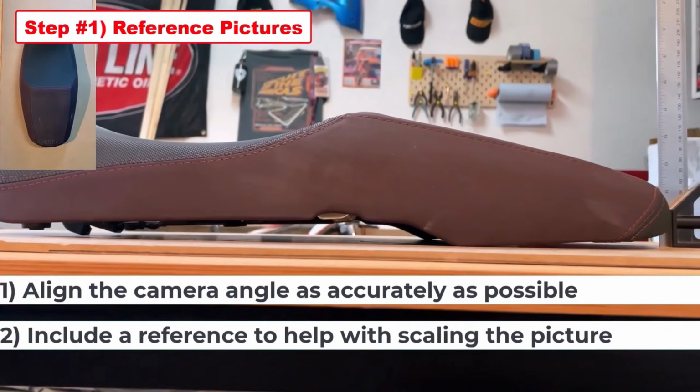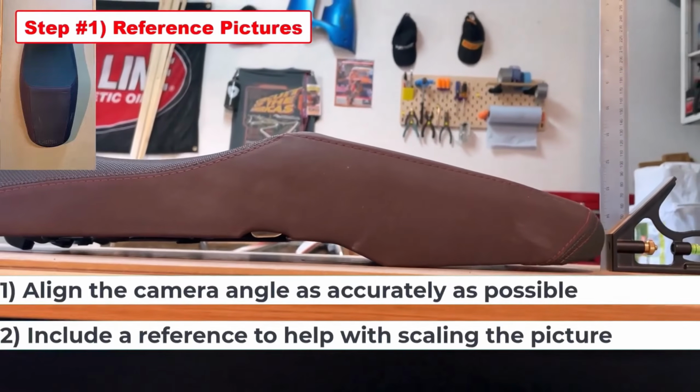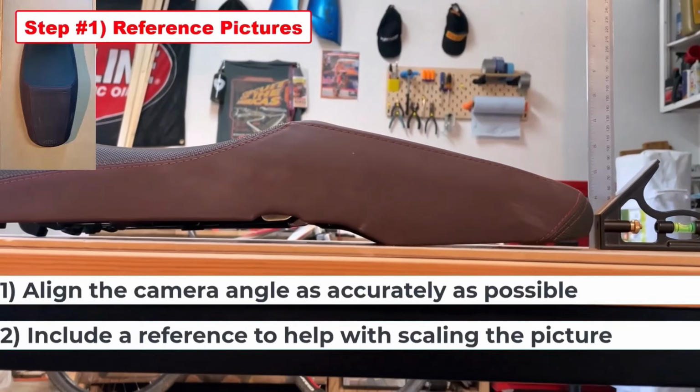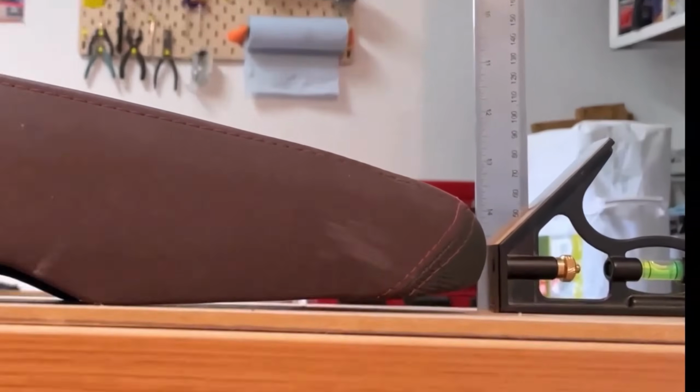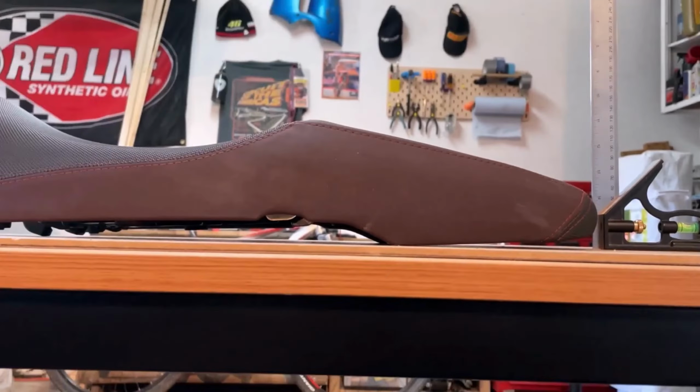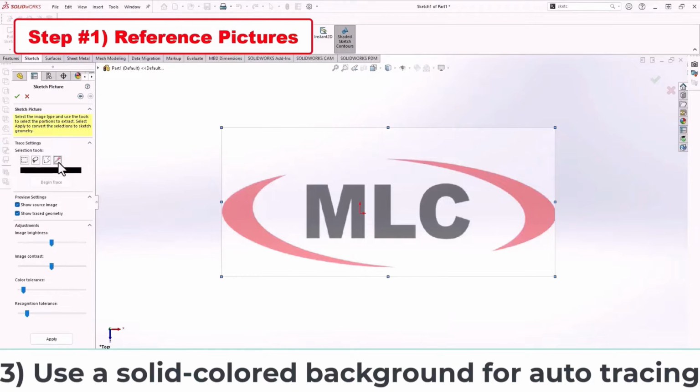Tip number two is to try some type of reference for scaling. So you can use a feature with a known dimension, but in my right view, I just added a ruler to help scale it. And we'll see how to use that later once we get into SOLIDWORKS. The last suggestion is try to use a colored background if possible. I didn't use it for this project, but if you have a solid background, you can take advantage of some auto tracing in SOLIDWORKS instead of sketching your own profiles. It works really well for something like a logo, for example.